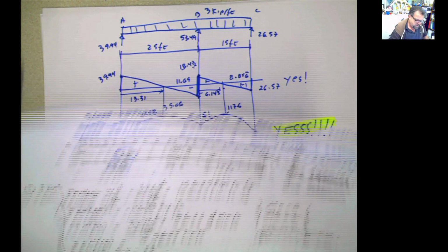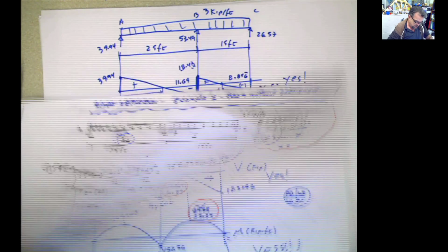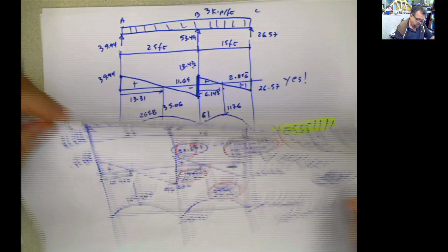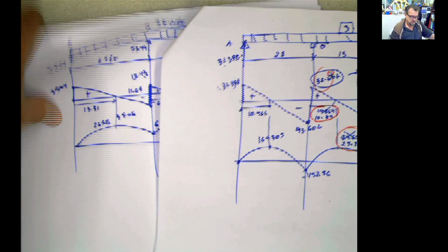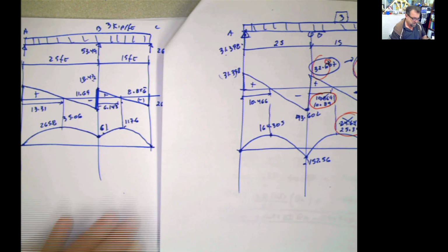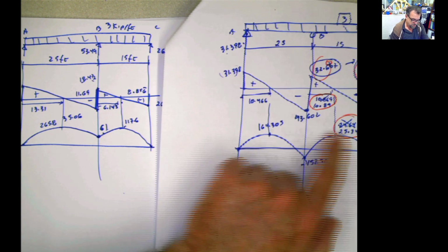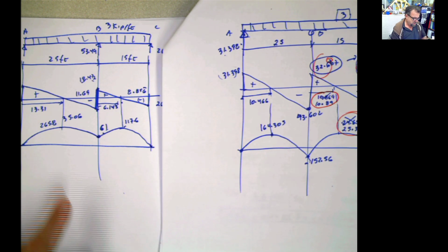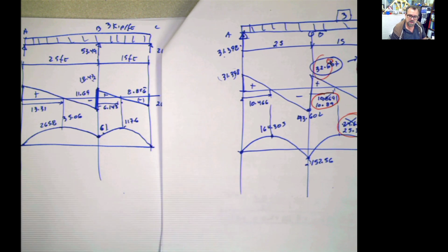Previous one, we did this just some minutes ago. Now, look at the diagram. By the way, the diagram with the corrections, these are the corrections that I said before. But look at the shape of the diagram before, and look at the influence now of the settlement. It's the same shape, but now look at what happened. Because the support settled, the moment redistributed. Look at the value of the moment here, 164. Now because the support settled, now it's 265. That's huge.